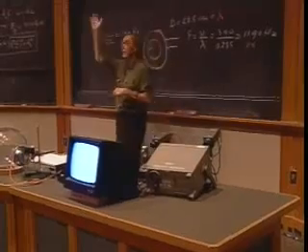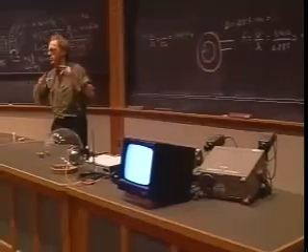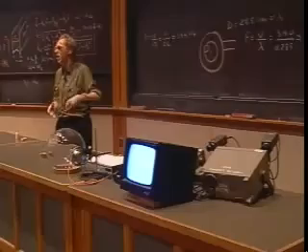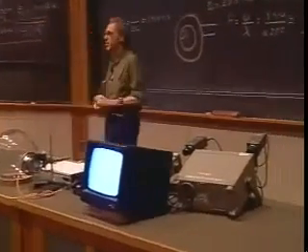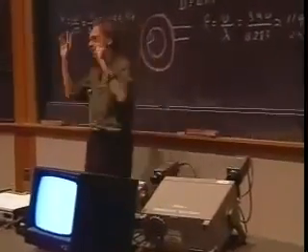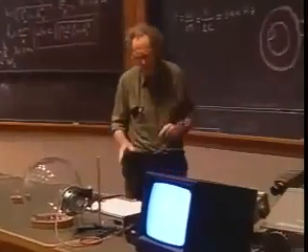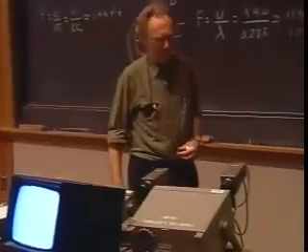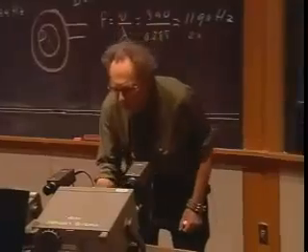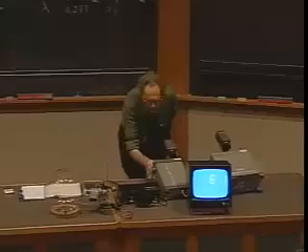Well, we were staring at each other in disbelief, and so we went on. I said to him, you know the 60 hertz are the lights in the building. That's what you pick up. It's some pickup, some crazy pickup. It's not a sound resonance. Whenever you see 60 hertz in the United States, or 50 hertz in Europe, you know it is some pickup. So I was willing to forget about it. In any case, we went on and we were trying to find the other